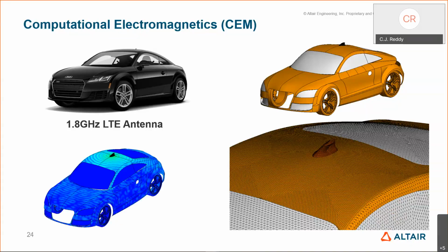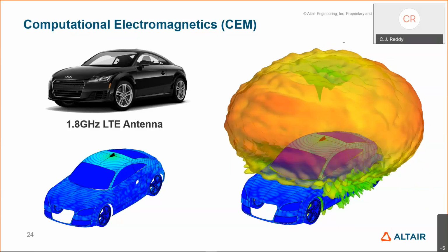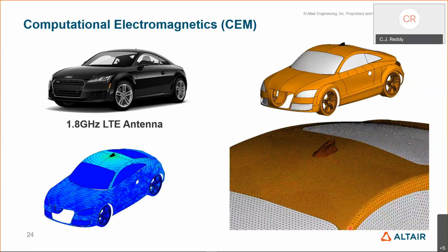And of course, once you have the currents, you can compute the radiation pattern. But the key is how small or how big these triangles can be. You can think of this as a sampling of your field. If your field is varying sinusoidally at a frequency, if you take 2 points, maybe it's too few, 3 points, 4 points.